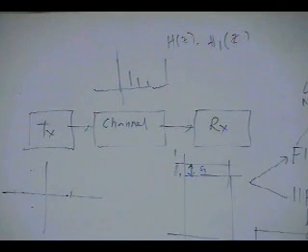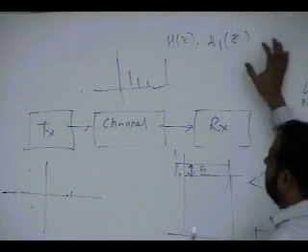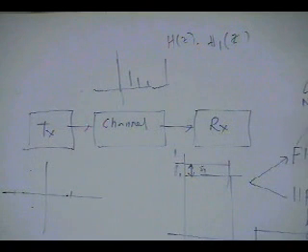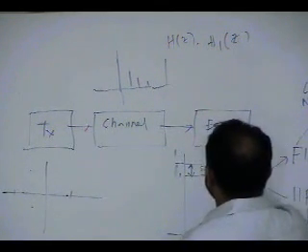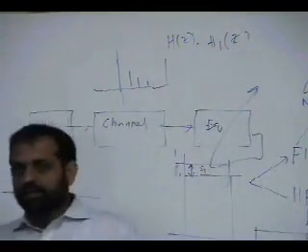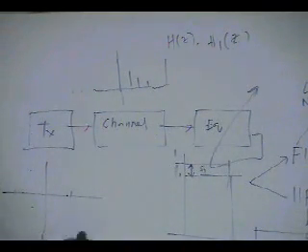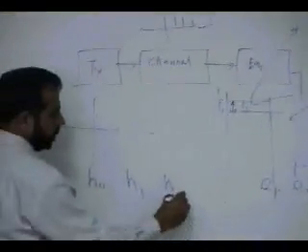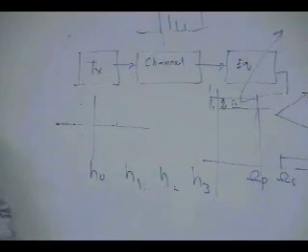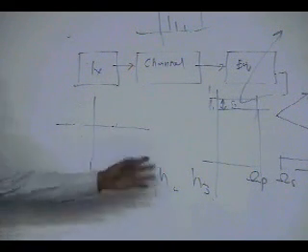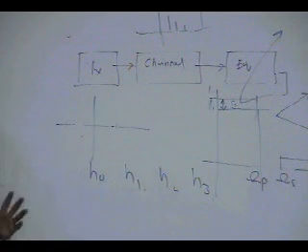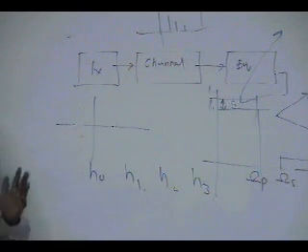That is adaptive signal processing, where you learn all these techniques, LMS and NLMS, and how it works: all the time, you are changing the coefficients of your equalizer. So what is an equalizer? It basically is an FIR filter. Let's say it is a 4 tap FIR filter, H0, H1, H2, H3. Sometimes you need an FIR filter with 512 taps. In telephony, once we were working on voice over IP, there you need a 512 tap FIR filter, and you have to keep changing all the 512 taps all the time, because they are changing.